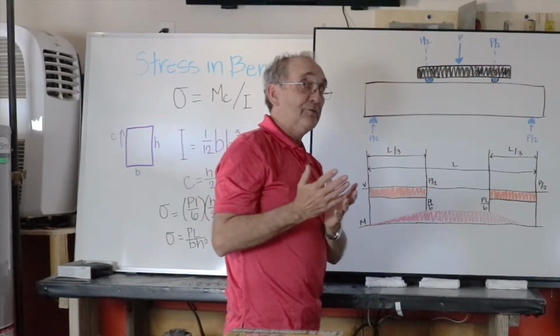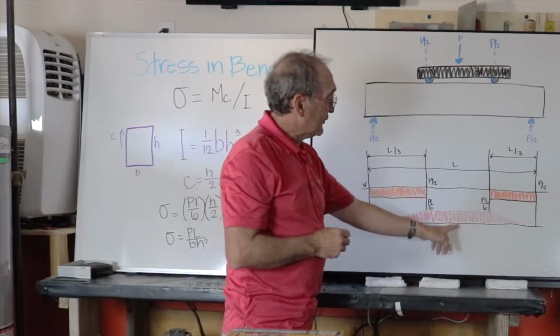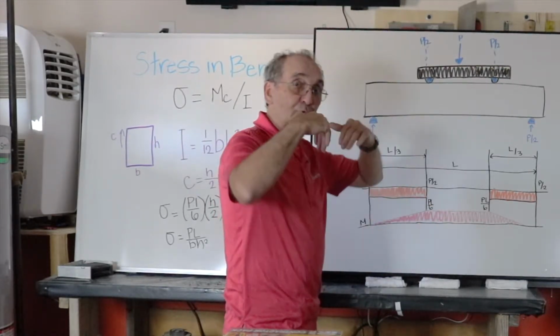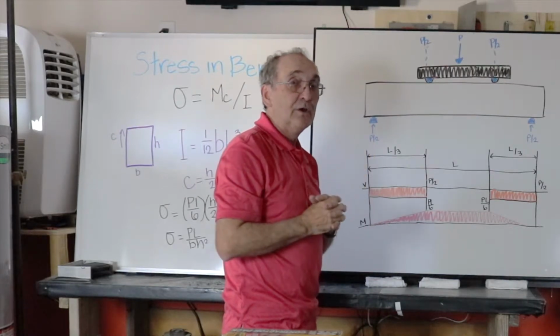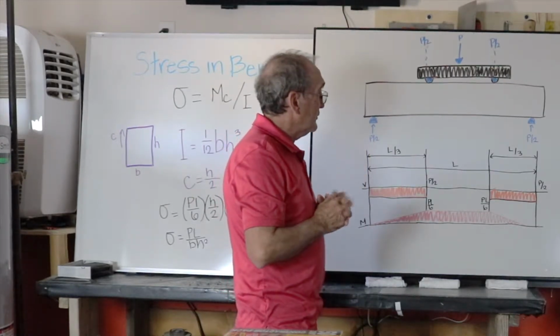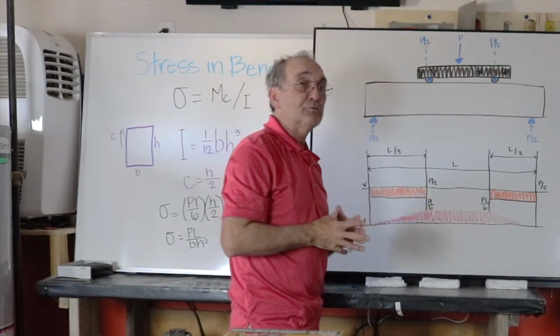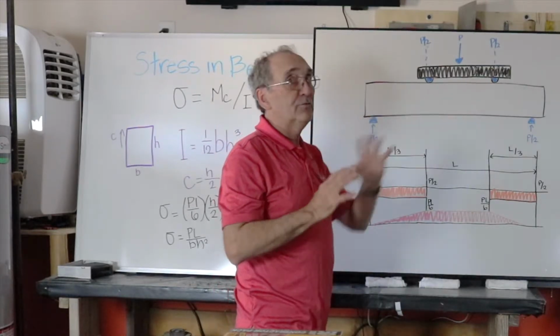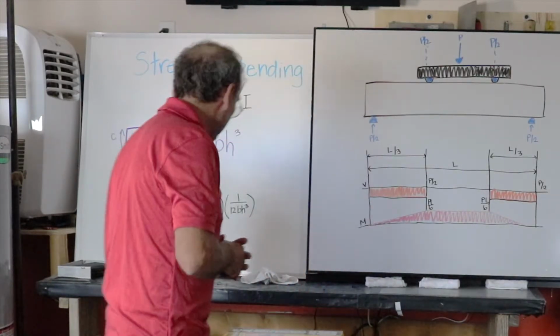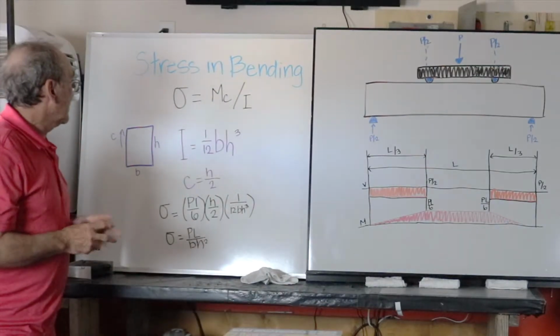So isn't that clever? We're going to measure the stress due to the moment, the pure bending stress in the beam, and use that to calculate our value. And no shear in that same region. So this boundary condition, very clever way to set it up. Let's move back over here.